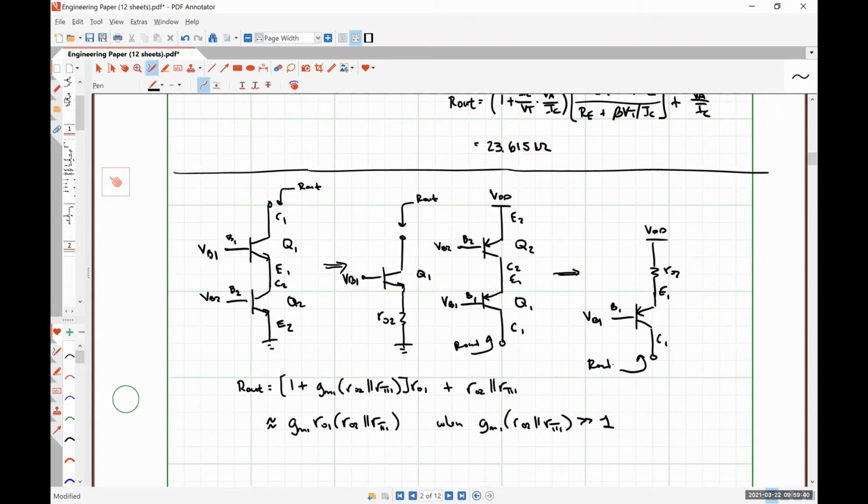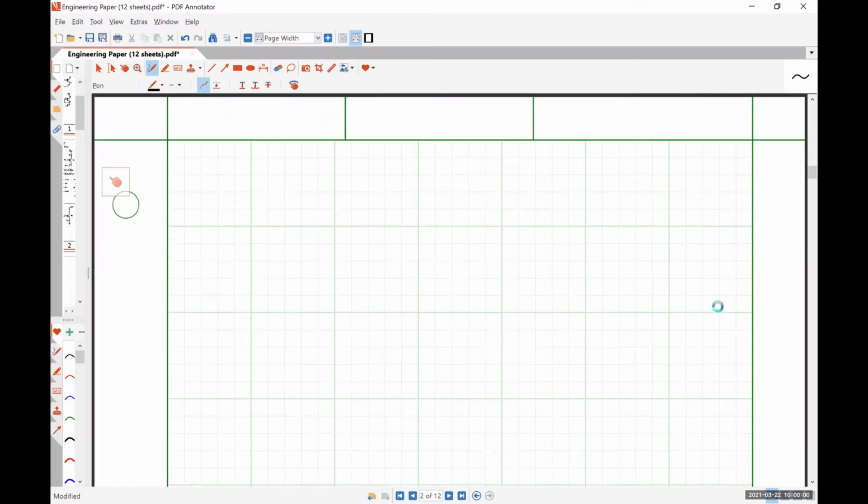So that voltage VCE2 can actually be pretty small, and this thing will still operate exactly how it's supposed to. So we can allow one of those transistors to slip into soft saturation, which gives us more voltage headroom at our output. So just as a quick example,